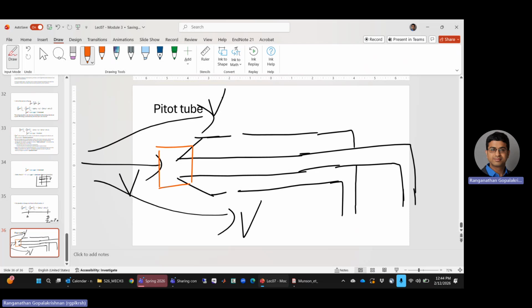Same goes here, and same goes here. In the transverse direction, the molecules do have a velocity, and they do enter this outer sleeve with that thermal or molecular velocity. So the pressure that you sense in the inner tube is the sum of the static and the dynamic, whereas the pressure that you sense in the coaxial outer tube is only the static.